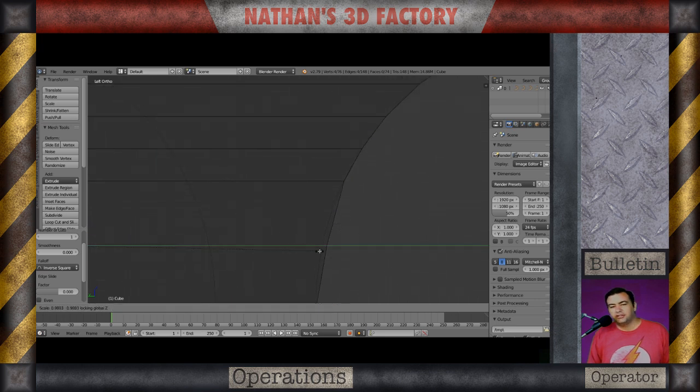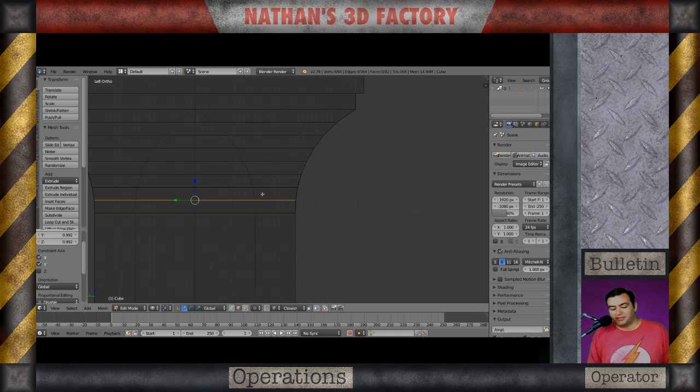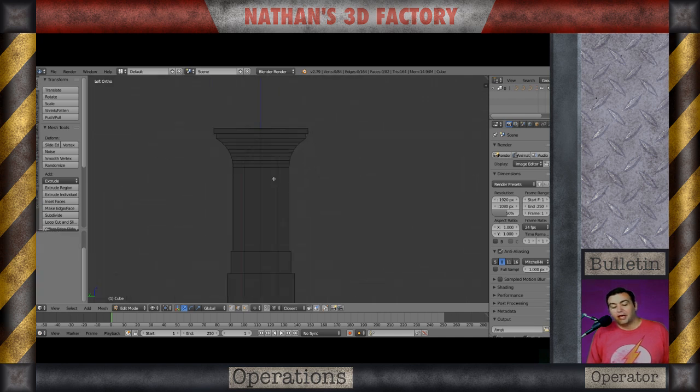So I could do a smoothness subdivision as I'm doing this, but I didn't want to do that because I tried that a few times and I wasn't liking the results. It wasn't quite coming out as accurately as I wanted it. So I am manually scaling these down. And it should be small enough that it's not going to cause any noticeable bumps or weird things like that when I'm doing the actual 3D print.